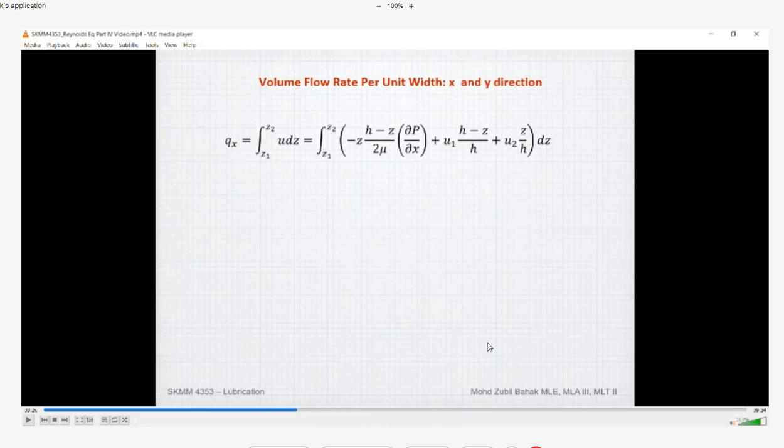And if you still remember, in order to determine the volume flow rate for a non-uniform flow, you need to integrate u or v dA, isn't it? I hope you still remember what you have learned in Fluid One. So we applied it here.